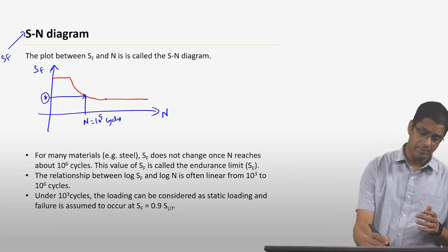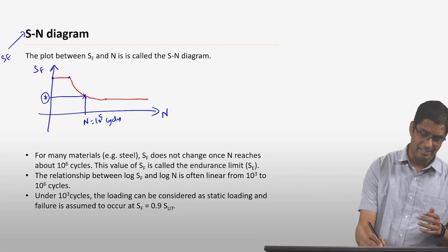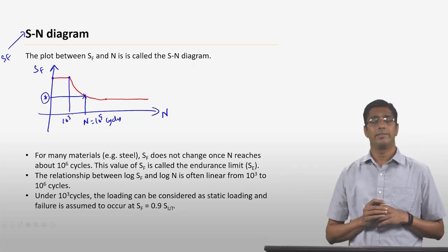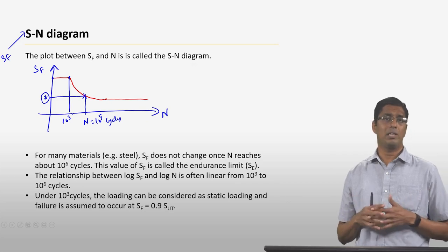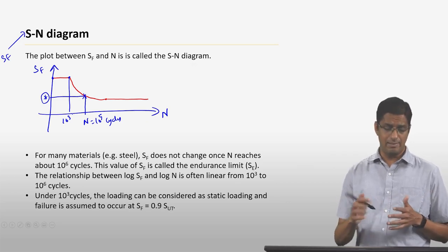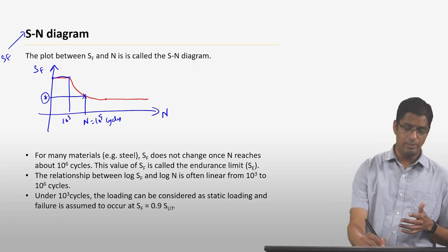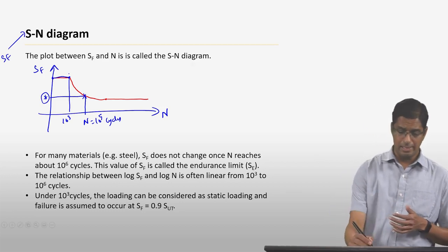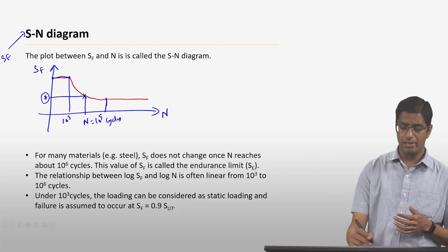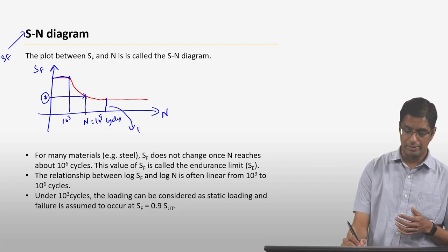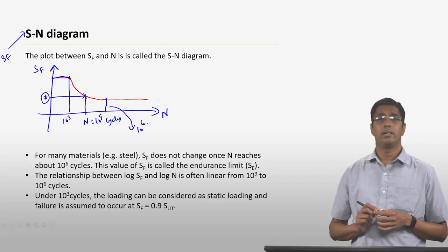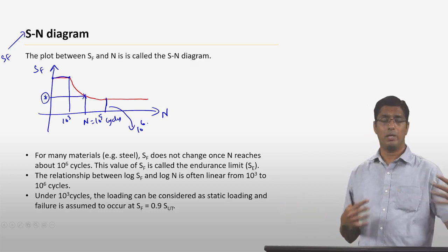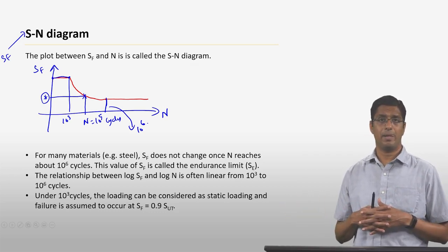Now, if you have a very small number of cycles, say usually around 10 to the 3 or smaller, then it doesn't matter what stress you apply. Okay, as long as it is below this particular value, the material is unlikely to fail. Similarly, if you go beyond a certain number of cycles, usually about 10 to the 6 cycles, it doesn't matter what stress you apply.